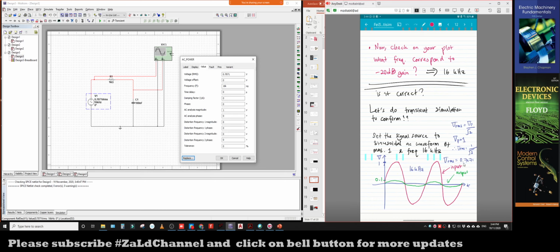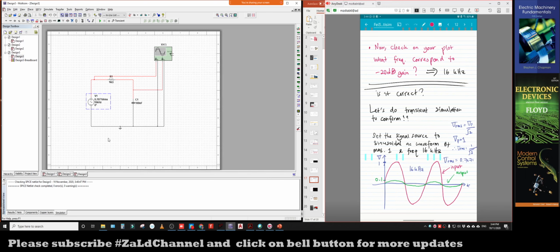So we get this, which is 0.7071. All right. So we just put RMS voltage of 0.7071 volt. Then click OK. So we have specified the input signal of magnitude 1. So we want to check the output. All right, so just do the simulation with the settings that we have done before.